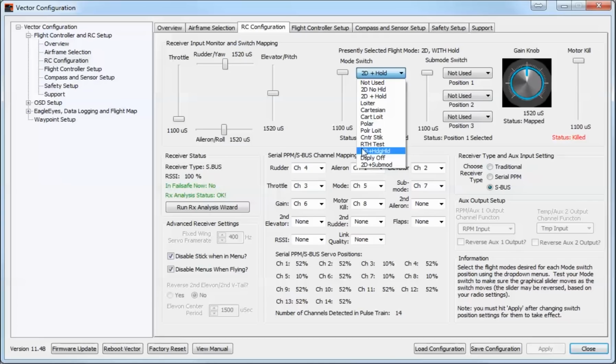What I would say is, if you are going to practice with this, first and foremost, get used to using it in center stick mode, which, as I've talked about, already has the self-stabilization. What this will do is give you the ability of at least being comfortable with a multi-rotor that's being used at various high attitude angles. However, what you need to remember is in 3D plus HdgHld mode, you have to do the stabilization of it.